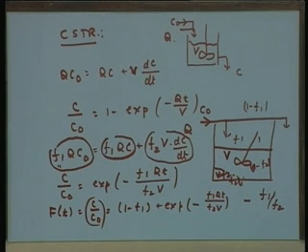Therefore, by comparing the two profiles, you can see what fraction, or what order of deviation, the dead zone and the mixed stream in the reactor have caused in performance. That is just to illustrate that the use of residence time distribution in the case of a real reactor can be used to determine the reactor performance, and such performance can then be used to calculate or correct the actual performance based on the kinetic data.